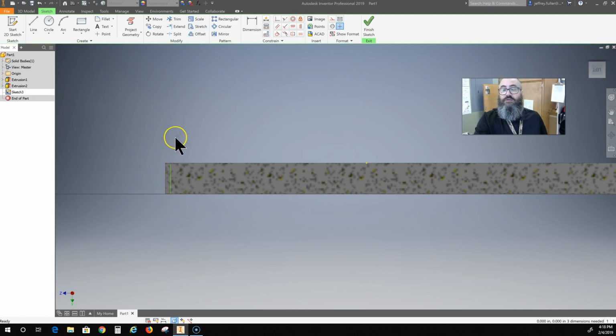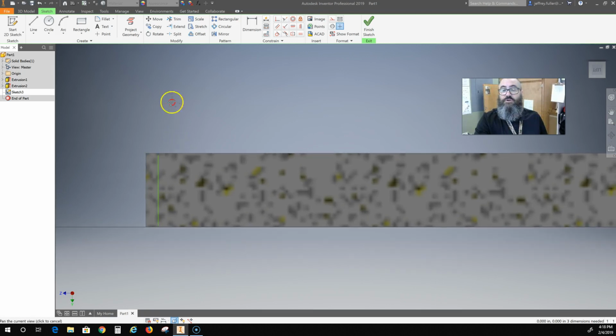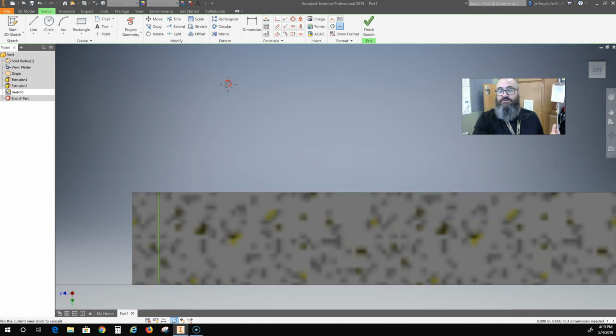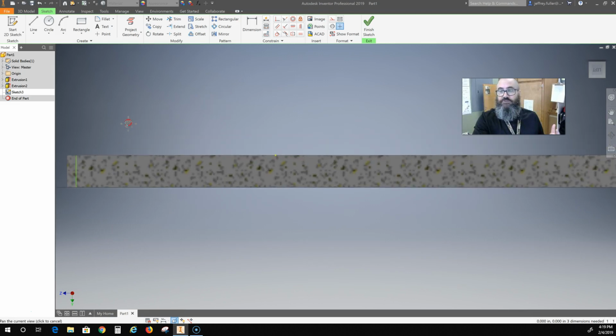Okay. And from that single line, I'm going to create an array. And actually, I probably need that to be, I'm going to redo that. I need it to be from here to here. And what I'm doing is I'm kind of picking where I believe is the edge of that other side that kind of goes up vertically, that would kind of be coming out at me as I'm doing that. And I'm just getting a rough dimension for my mullion placements.